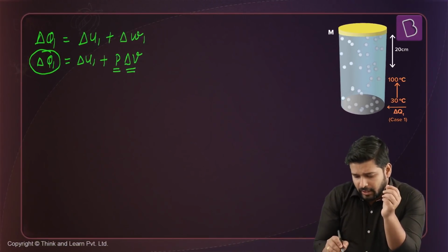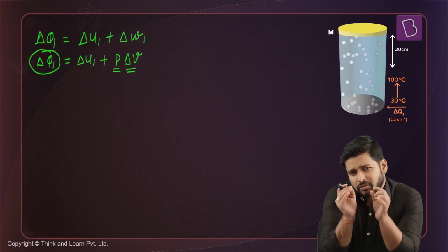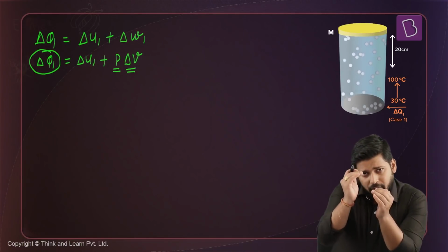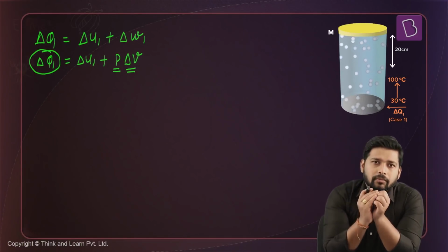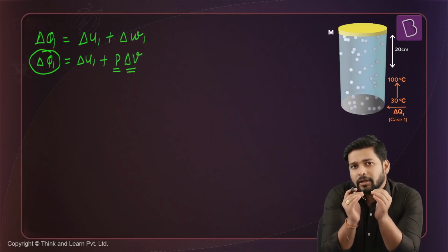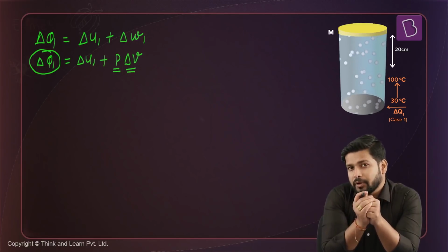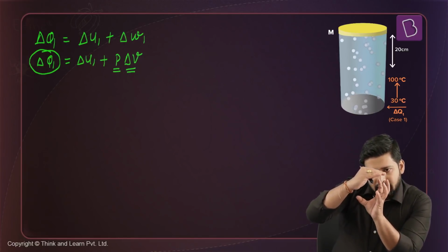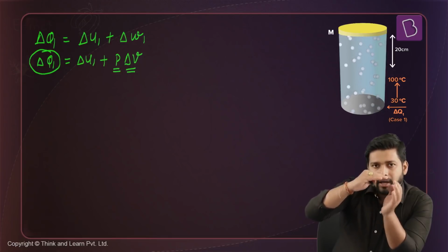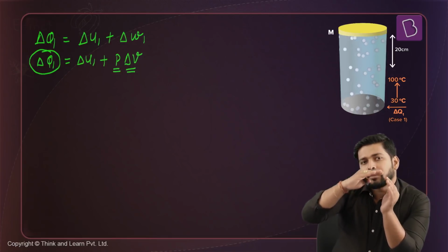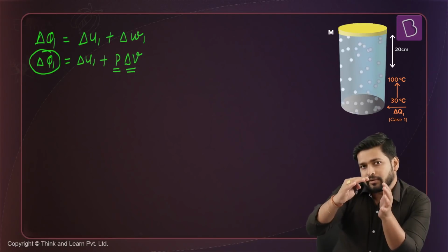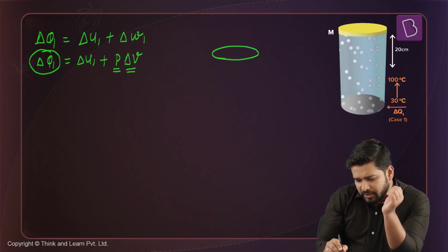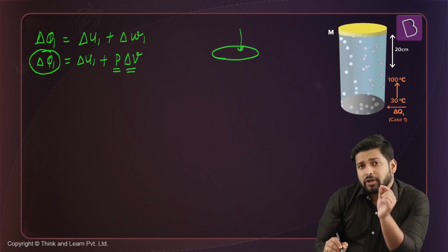That's the pressure of the gas. If you just think slightly about what happens when the piston is moving upward, why will this piston stop? A point will come when the pressure on both sides of the piston will become equal. Below the piston, it's gas, and at the top, it's atmosphere, and we have also been given that there is some mass of the piston. So if I draw a diagram like this, the piston is going to stop when it reaches a point of pressure balance.